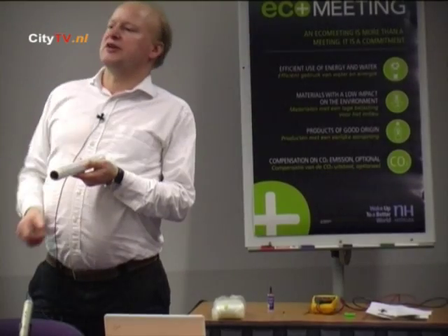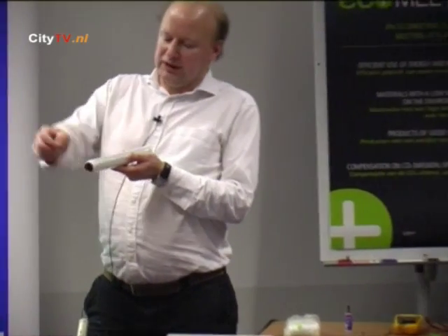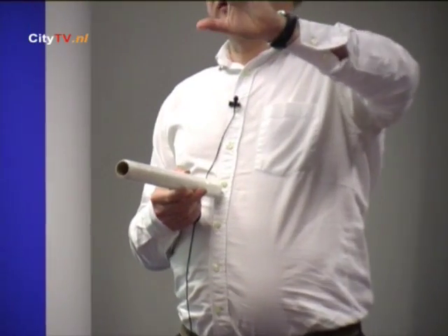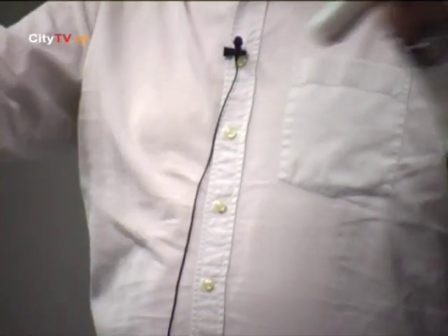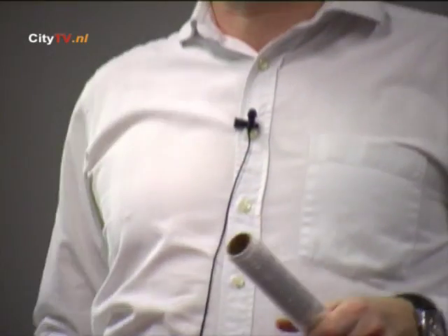Of course, this graphite is very messy. So you rub it out, and there will be maybe some relatively big flake sitting there. But then, each time you go with your cotton wool, you take off more and more layers. And finally, you get a conducting path. First of all, you're below the percolation threshold, very high resistance. And then you put on more, you get a conducting path. And then when you get this conducting path, your resistance is 5 kilo ohm.